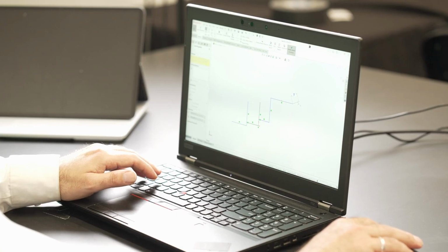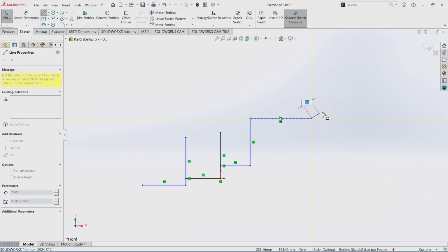If I, for some reason, want to ensure that this goes into a specific length or specific angle, I can always hold down the Shift key. So by holding down the Shift key, I lock it to a specific length. Here in this case, we have 20 millimeters, 40, 60, 80. And we also have the same thing with the angle. See if I can get this. I think it's 44 millimeters as standard. There we go. Now it's 45 millimeters and 45 and 45.